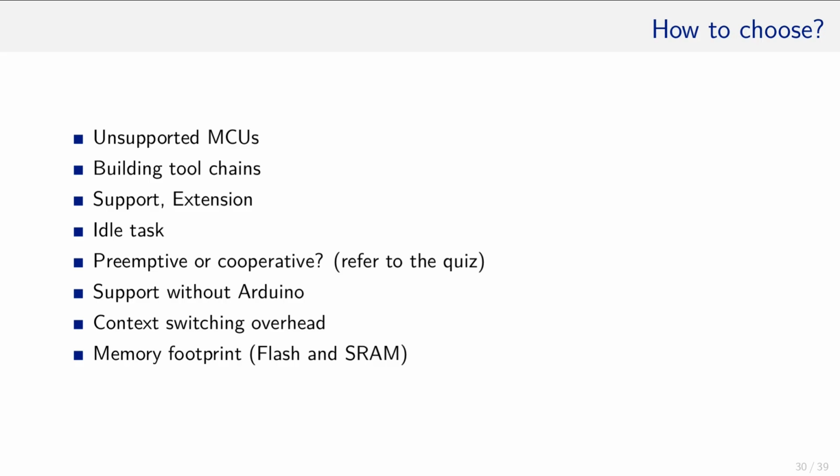Hence, let's see what the requirements are and the questions to be answered. First, the MCU is to be supported without spending too much effort in porting a scheduler to a new architecture. In addition, we have to consider our current toolchain setup. Currently, in the VirtualBox image, the avr-gcc for Linux is used to compile user programs and not WinAVR.